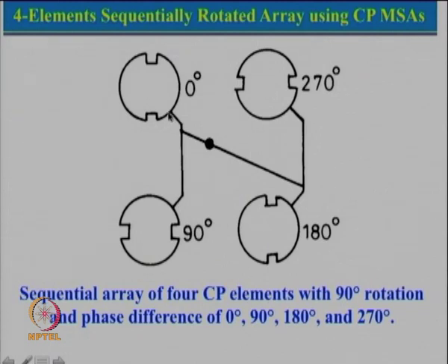So, if you see here, this particular length you assume has to be common to all the other configurations. So, starting from here, this plus this, you consider this as a reference length, let us call it L1. So, now this part is common to this path here. So, what we need here, this path plus this path here, which is common. After that, this should be lambda by 4. So, if that is lambda by 4, the path delay from here, if I say this is reference, this will become 90 degree additional.